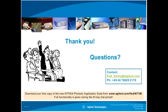Yeah, that's a good one. Usually it is of high interest to have really accurate PDL measurements, and on the other hand, it's also desired to have reliability when connecting components, and so you want to be independent of possible dirt on the connectors, and so many people like to use angled components, angled connectors.